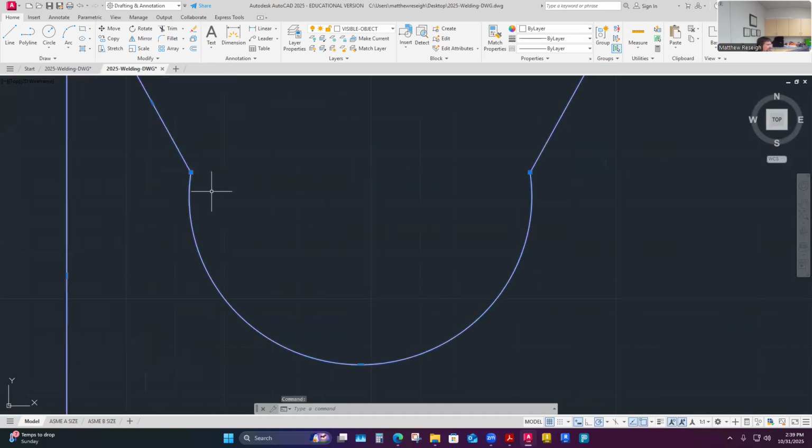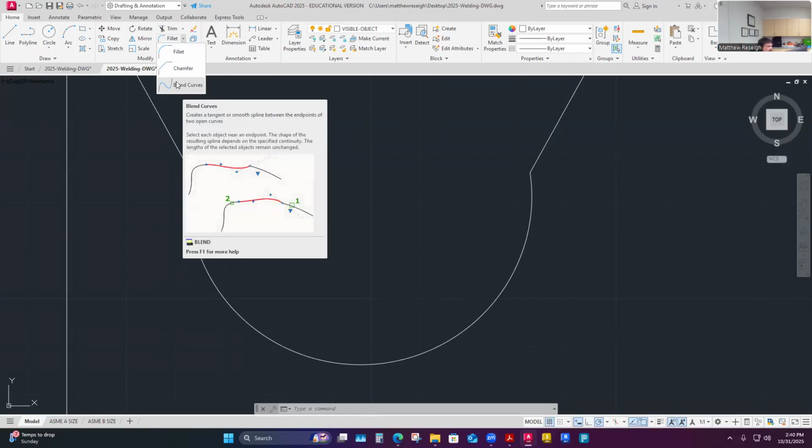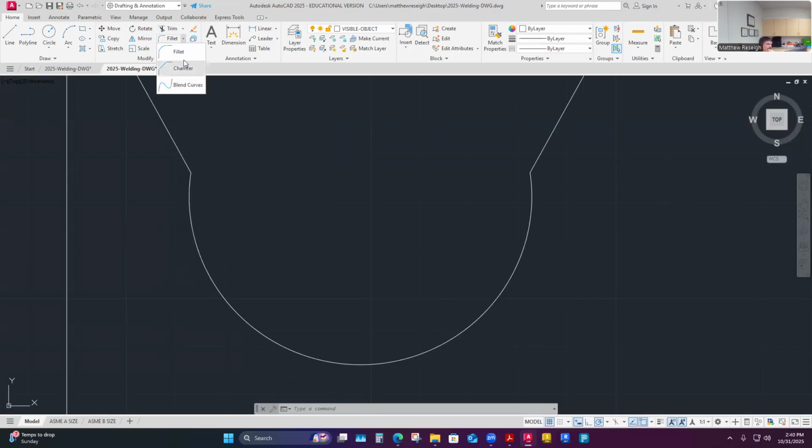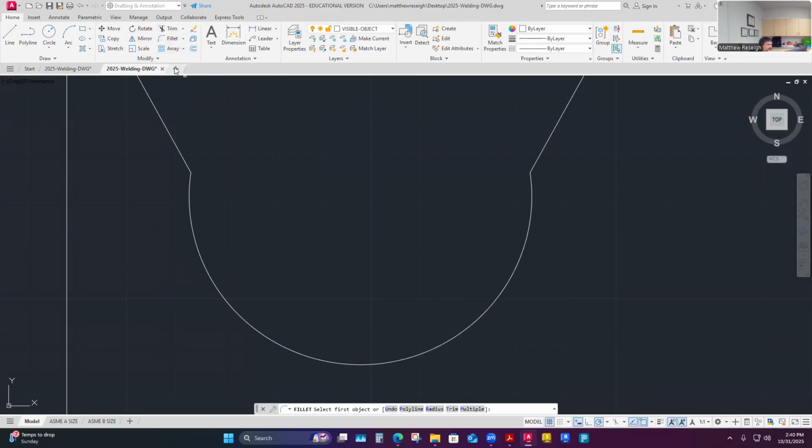It's a joined unit now, so it doesn't recognize it as totally separate geometry, but let's use this. It's a modify command. It's fillet. The opposite of fillet is a chamfer, or we have this other one that's way less used for just standard parts in the mechanical world. But chamfer and fillets are used a lot, and it'll have just whatever I used last. So if you can't find fillet, it's probably buried. It's the opposite of chamfer. Those are usually the two that I display. I think fillet's default, but it shows up.